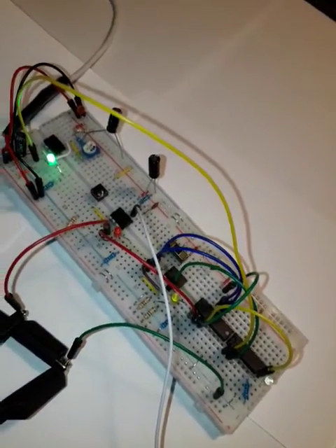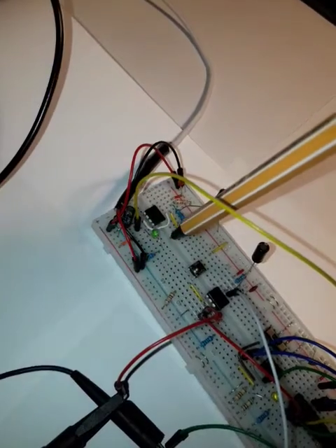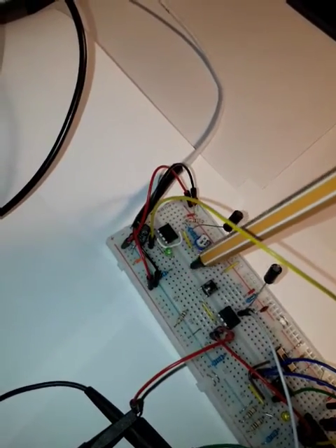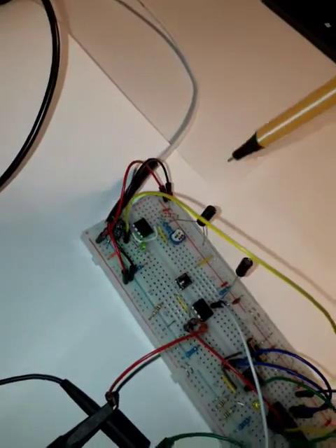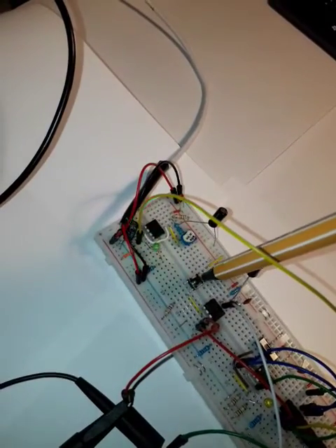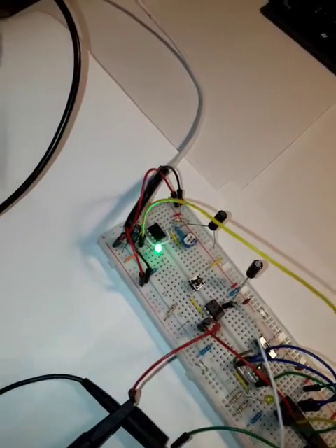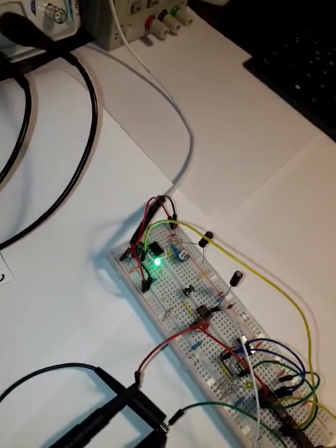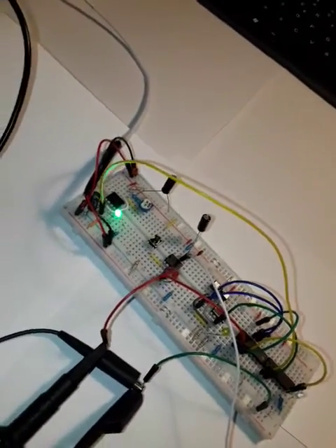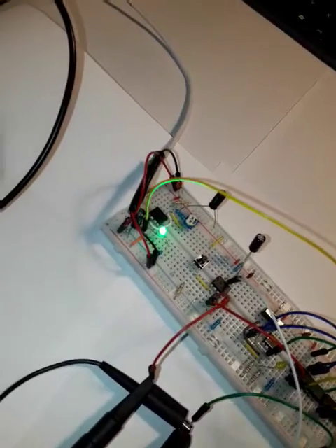So now, because we're going to use this to provide a clocking system for our computer, we are going to have to combine these two. So the astable mode will give us the pulses we require for our computer to run its operation, and the monostable mode is going to provide us with the pulse we need during debugging. So you just want to go step by step to run the computer and make sure that everything's fine, to see if there are issues. And now the question is, how do we combine these two to give us the final clock output?